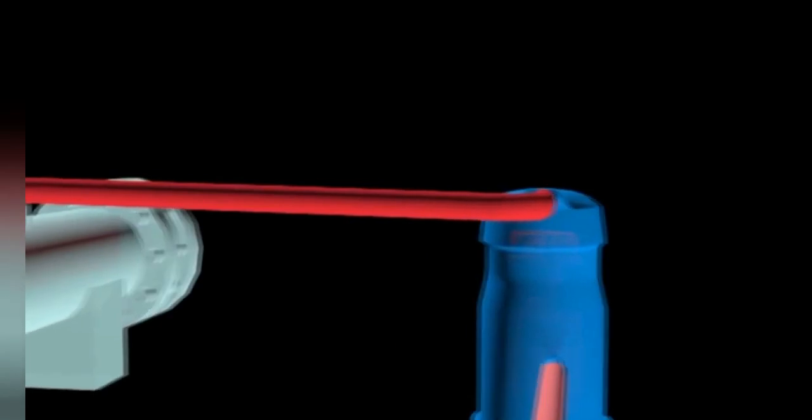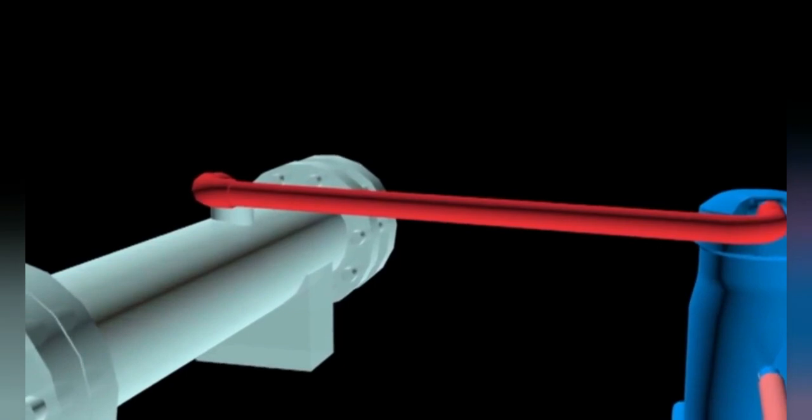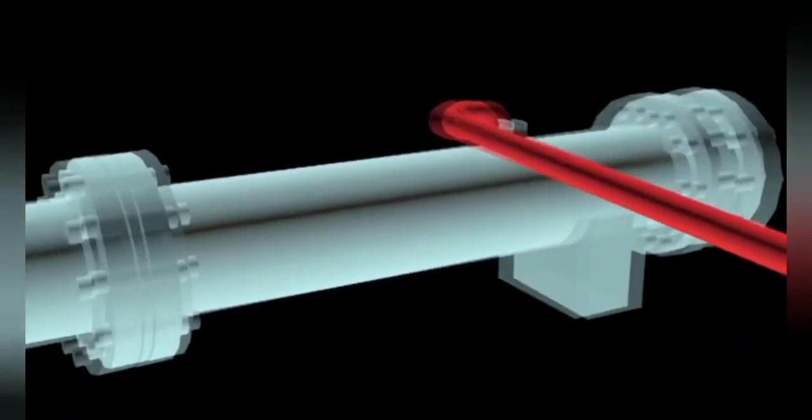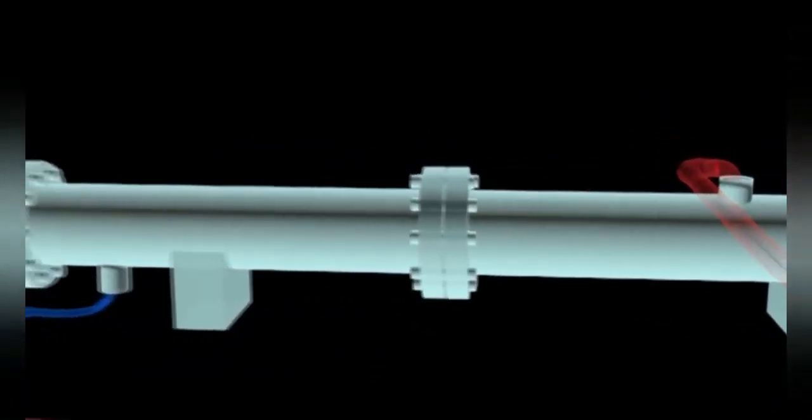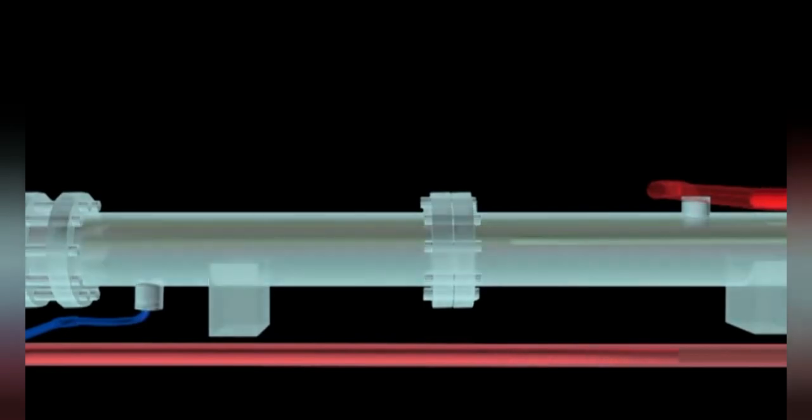Condenser. The refrigerant in high-pressure gas enters the condenser at a temperature higher than the temperature of condenser water. In the condenser, the heat will be eliminated to the condenser water from the cooling tower through the process of convection and conduction. After the heat is removed, the refrigerant in high-pressure gas is condensed into a high-pressure liquid when out of the condenser. The condenser most commonly used is shell and tube type. Water is flowing through the tube while refrigerant liquid is flooded in the shell.